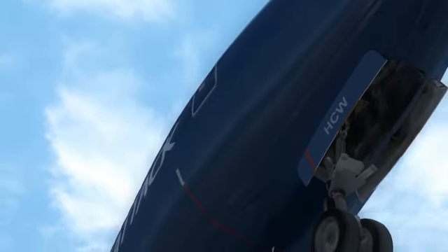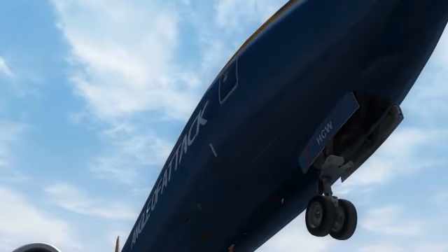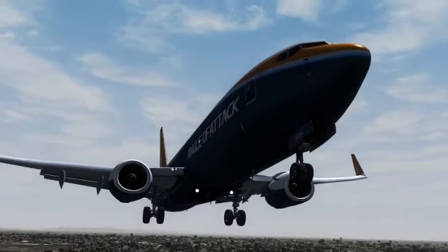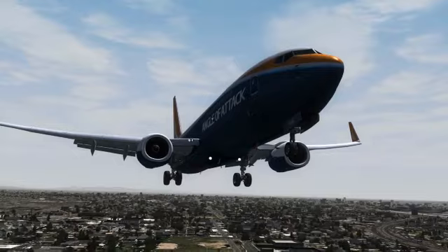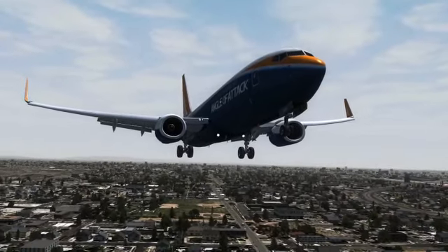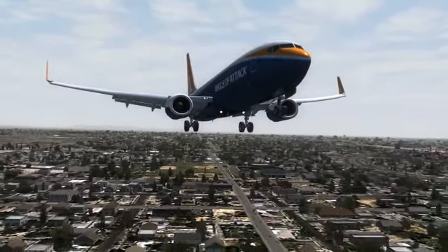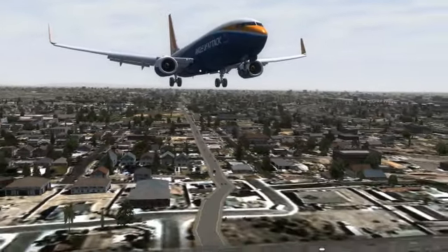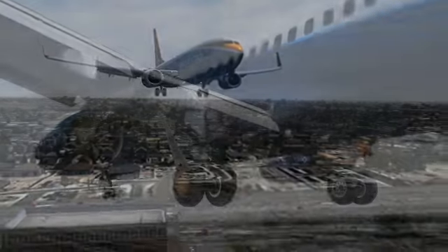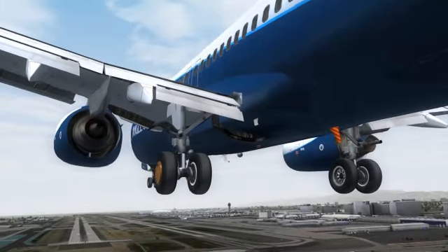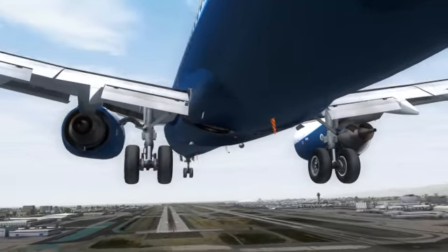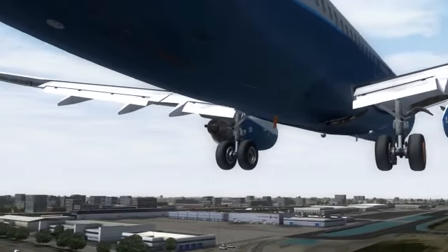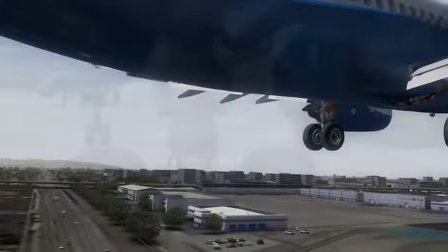During the rest of the flight, operating the engines is pretty straightforward. For the most part, the autothrust system handles the thrust that each engine produces to match the required flight speed that is programmed into the flight management computers. This, of course, varies according to many weather parameters, company fuel burn policies, and the respective flight phase. When the aircraft is bound to touchdown during the landing phase, the engines are placed into idle thrust.